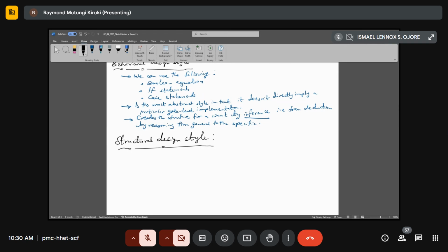That's it. So the same concept applies for the structural design style. You break your circuit, because you can imagine the circuits can be very complex, and you don't want to put everything in a single file. Not only is it prone to errors, but it's also actually difficult to do that. But if for each part you do its own VHDL code, and then you bring everything together using a top level file, it makes things much easier. So that is the concept behind the structural design.